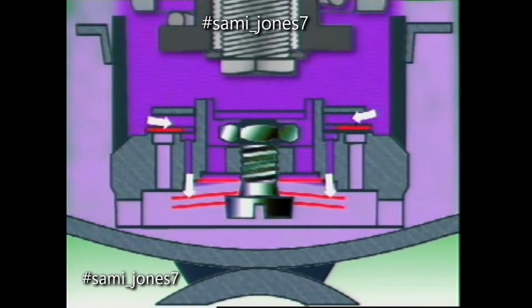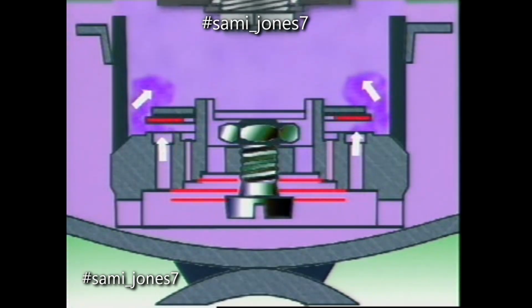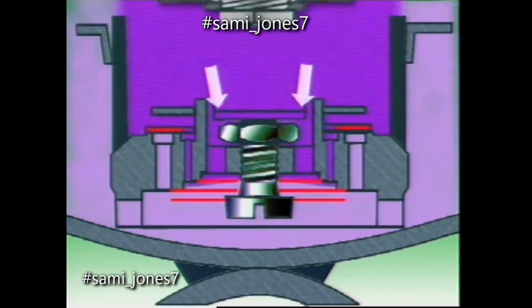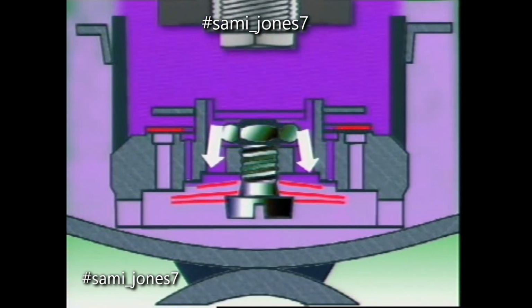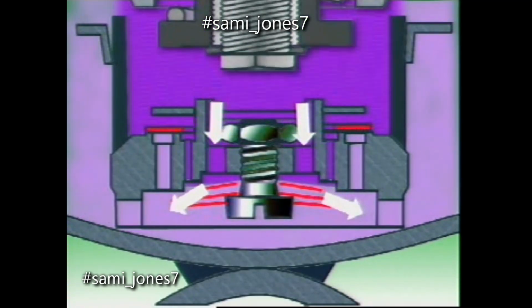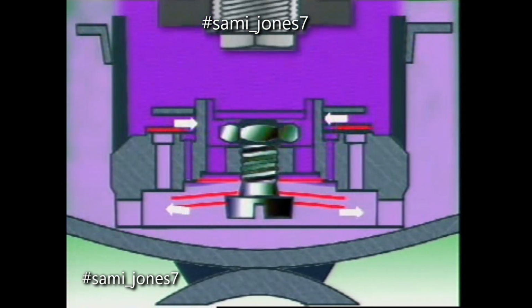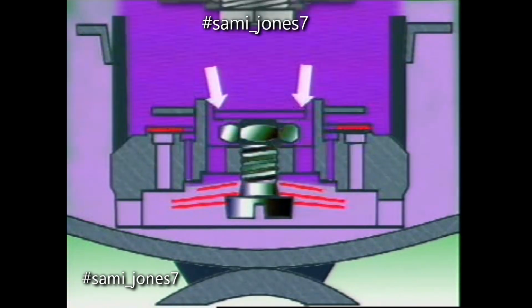The valves provide control over the amount of force required to pass fluid through them at any given piston velocity. They can be made to open in stages according to fluid pressure. This allows light resistance to motion when the piston moves slowly and heavy resistance when piston velocity is high.